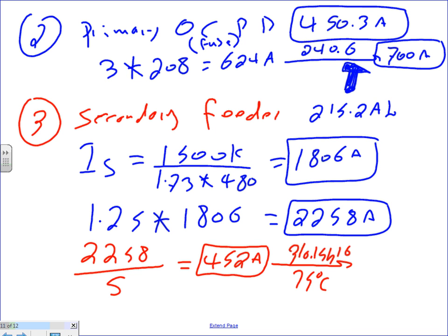I can go to 310.15(B)(16). I'm going to carry how many conductors? I don't want to do the rating for the neutral here, guys. You know how to do it. I'm going to carry full neutral, but you should size the neutral. I'm going to carry 4 conductors.